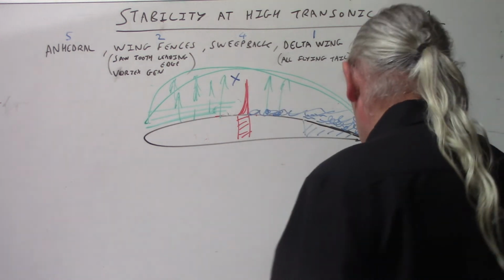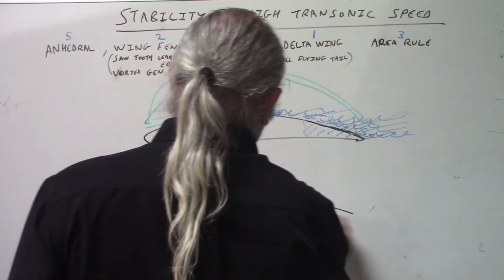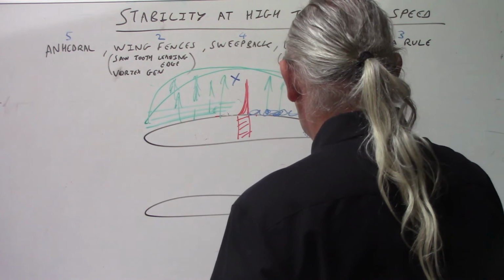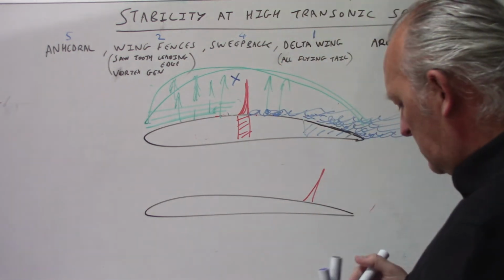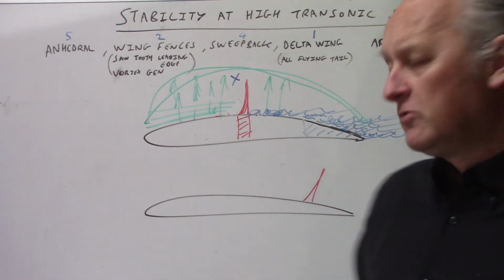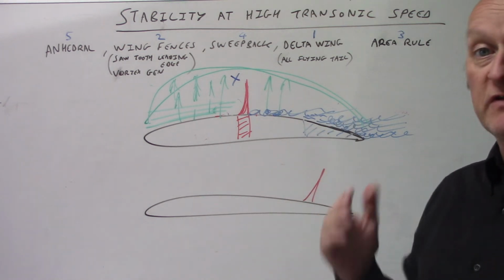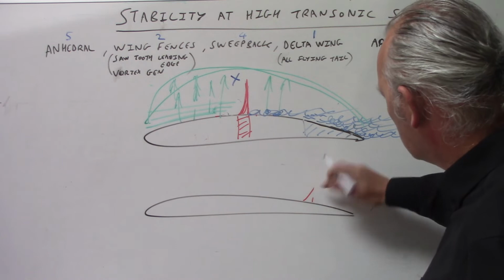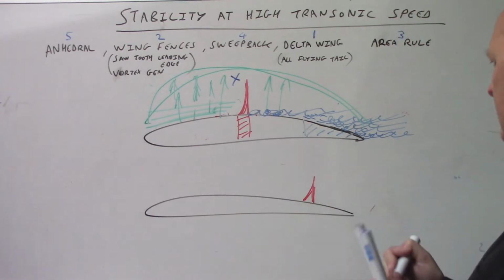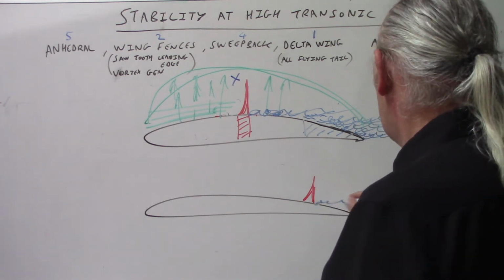Okay, once you get to Mach 0.95, you get to this sort of effect here, where you have a shock wave, and the shock wave can get smaller, and sometimes it'll angle back a little bit. Generally, you have a normal and oblique shock wave. A normal shock wave, as found on a wing, will be 90 degrees or perpendicular to the relevant airflow. Okay, so I've drawn that wrong. It wouldn't sit like that. It'll sit like that. Okay, and you might find the shock wave gets slightly smaller as it goes further back, and then your separated flow, right?